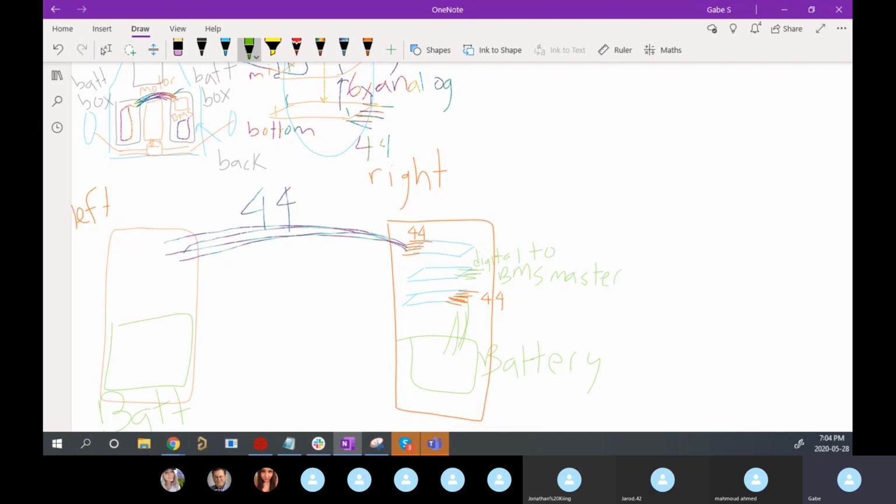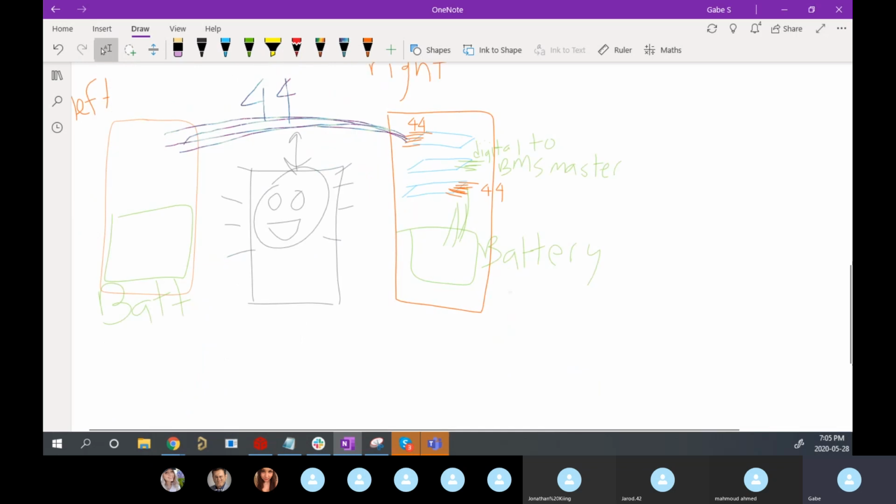And these are all analog, right? This is not very immune to noise. You have the biggest generator of noise in the car literally right beside. These guys are neighbors, right? Generating as much noise as can be. So this could completely ruin all the measurements. Ideally, we don't want that.